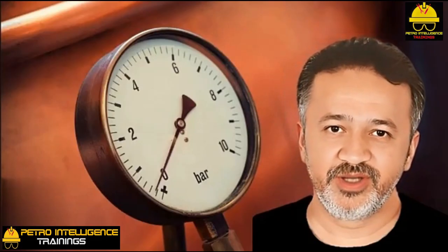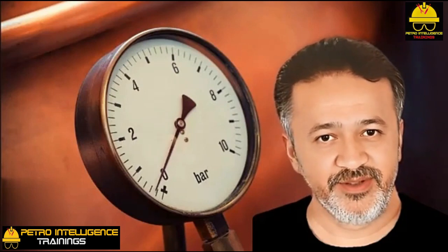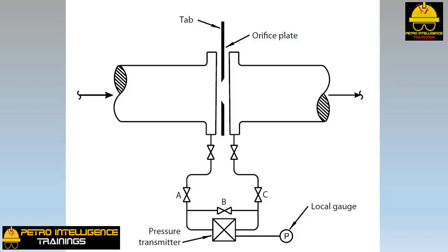Zeroing out a flowmeter. The indicated flow of acetic acid is 9,000 liters per day. The instrument technician checks the flowmeter to see if it has drifted by opening valve B with A and C closed, shown in the picture. It should go back to 0, but a reading of 2,000 liters per day is noted. The full range on the flowmeter is 10,000 liters per day. What is the real flow rate of the acetic acid?